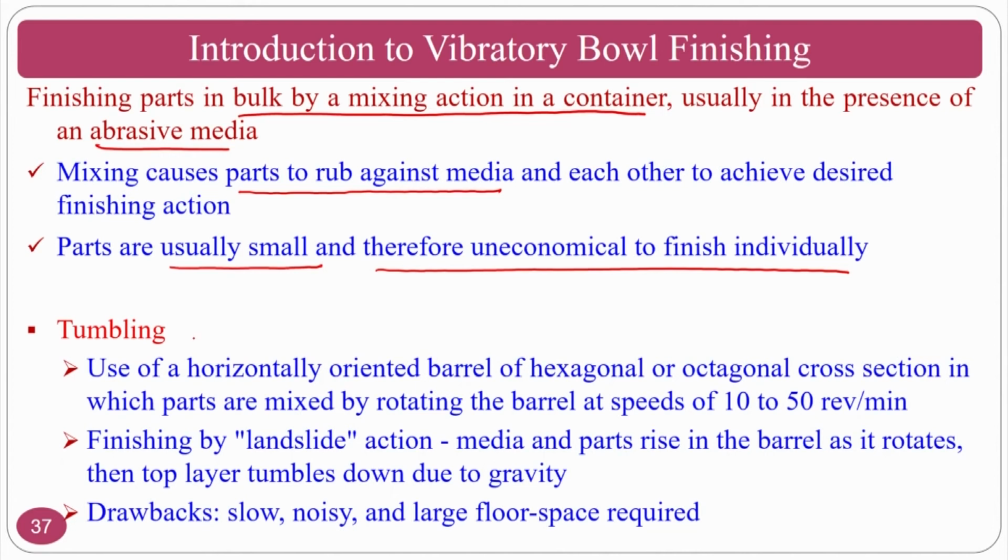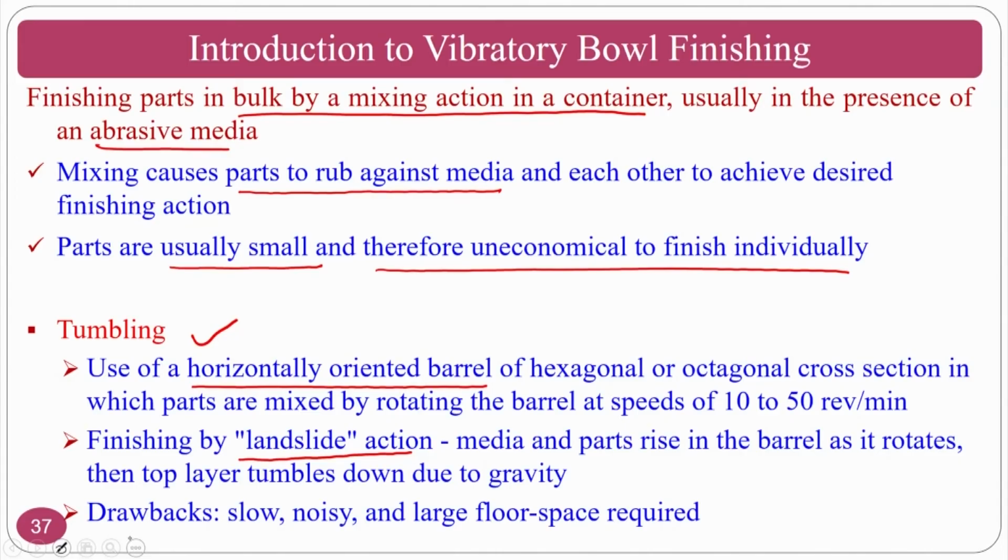Another one is the tumbling process. It is normally in a horizontally oriented barrel, and the mechanism is like a landslide. Whenever you have abrasive particles as well as the components, you just rotate it, and a landslide type of material removal reaction takes place. The basic drawback of this process is that it is slow, and at the same time noisy.